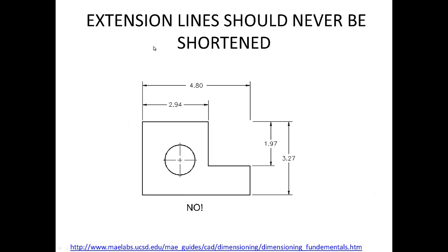Another one, extension lines should never be shortened. You should leave this line going up to the part. And the same goes for this other one. It should go all the way to here.